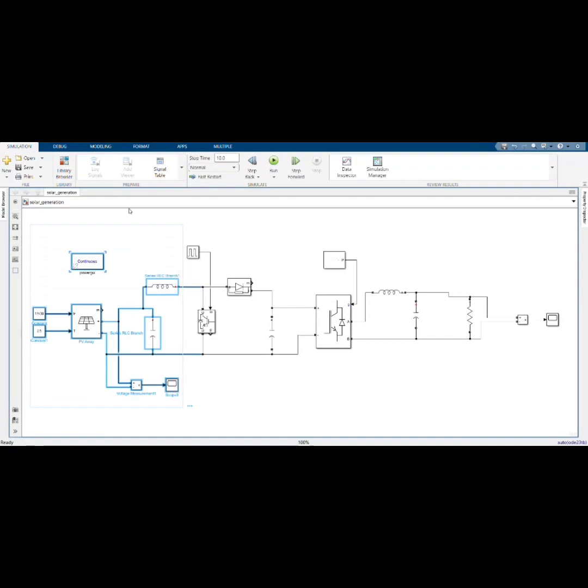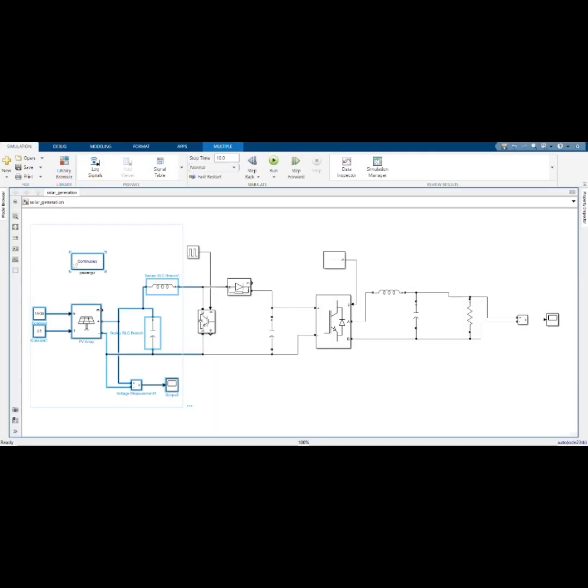Moving on, I'll start by explaining the simulation circuit created by MATLAB Simulink to simulate what's actually going on inside a solar panel when producing the electrical current. First and foremost, to generate an electrical current, the sun's rays are attenuated as they pass through the atmosphere, leaving maximum normal surface irradiance at sea level on a clear day at around 1000 W per square meter. The minimum solar insolation needed to generate electricity is 100 to 200 W/m², which is enough to power at least one lamp and fan.